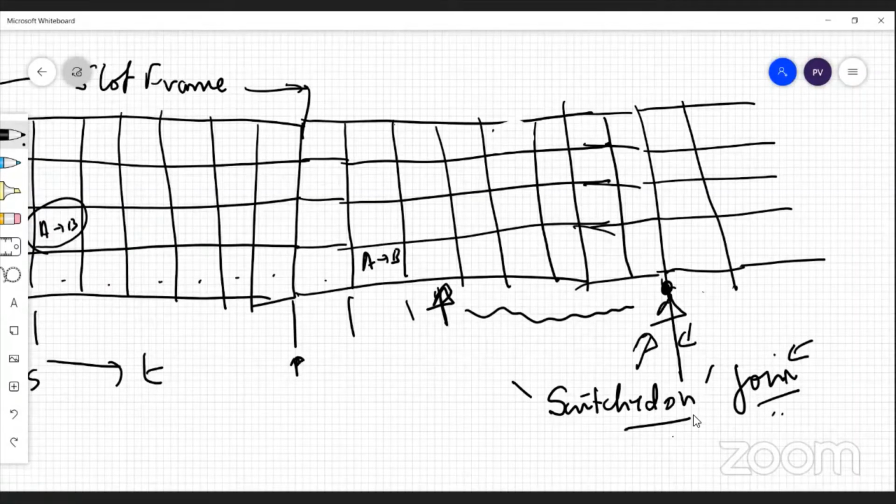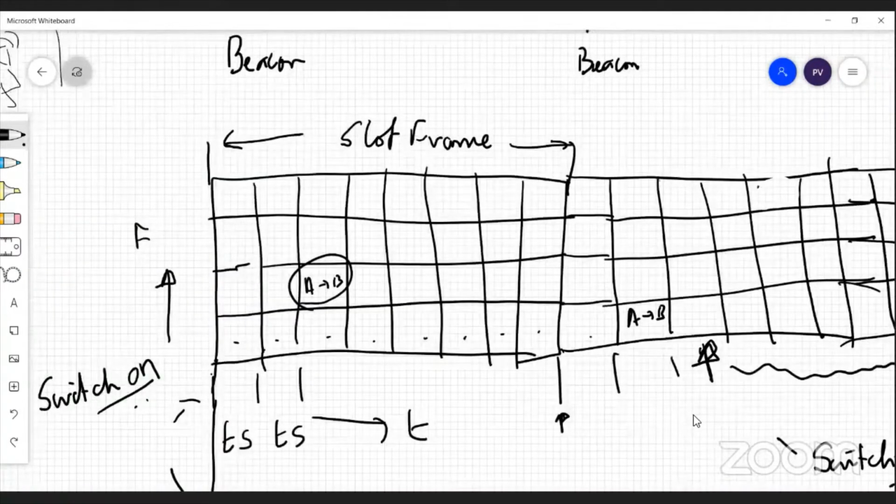And if it is synchronized and it knows how to hop the channel, because as I said, on the y-axis is F, frequency. This is frequency channel 1. This can go up to 15. There are 15 channels in 15.4e. 16, sorry. Sahana and Sita are here, they correct me. There are 16 channels that you can go, and your slot frame can be defined by the PAN coordinator.